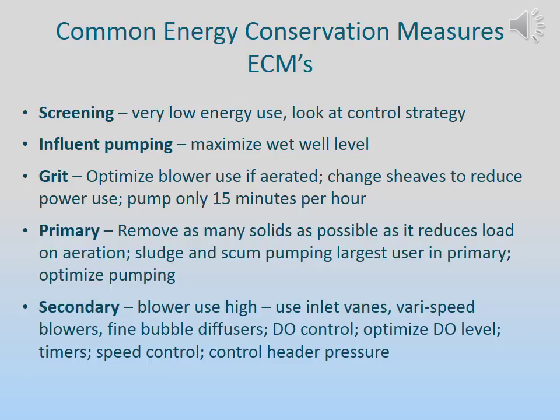With primary sedimentation, the goal is to remove as many solids as possible, as this will reduce the load on the aeration tank and associated running of the process blower. Sludge and scum pumping are the largest users of power in primary, so look for opportunities to optimize the pump cycles. As far as secondary treatment is concerned, aerated tanks are a must.